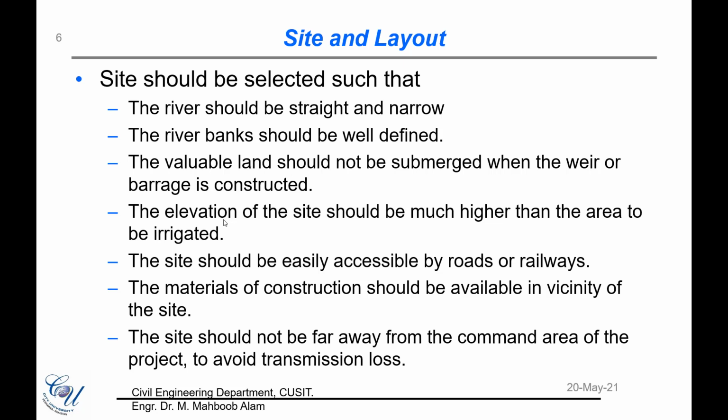targeting the higher velocities. As you know, if we have lesser area, the velocity would be greater. If we have greater area, the velocity would be lower. So we kind of target the areas where the river section is kind of narrow, so that we can have enough velocity for the water.